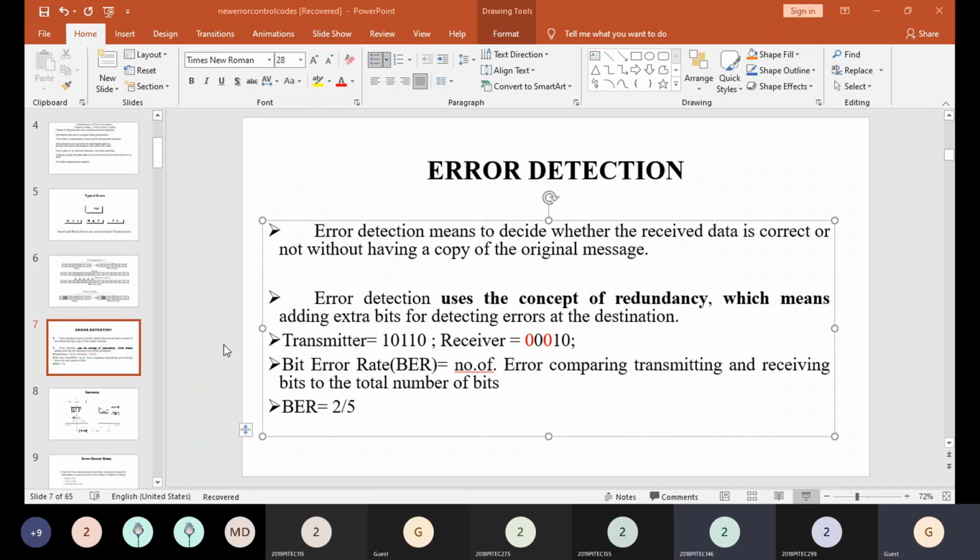The dimension of the parity check matrix is n cross n minus k. So n minus k, or it is nothing but m by n. So m is nothing but the number of parity bits. Then syndrome. For error correction and error detection, you need to know the syndrome. So S is equal to R into H transpose, which is equal to E into H transpose, which is 1 cross n minus k. E cap is the estimated error vector 1 by n, C cap is the estimated code word, and M cap is the decoded message vector.